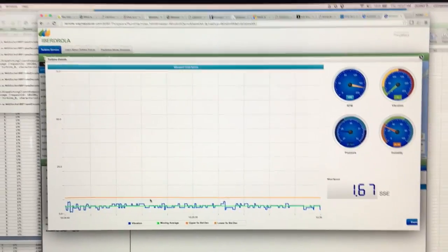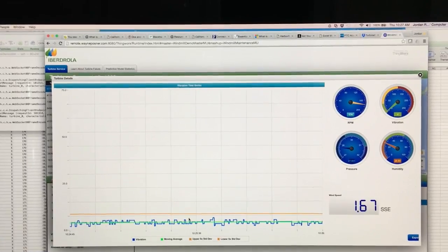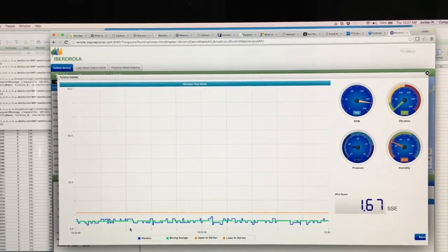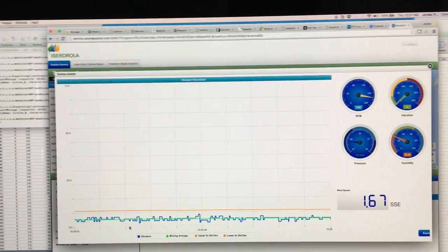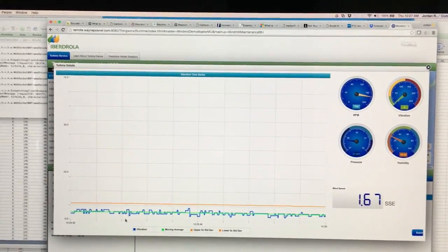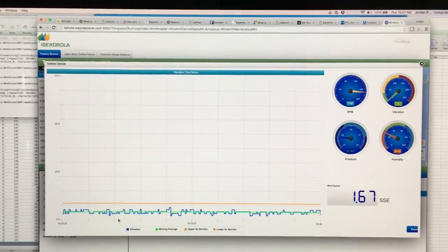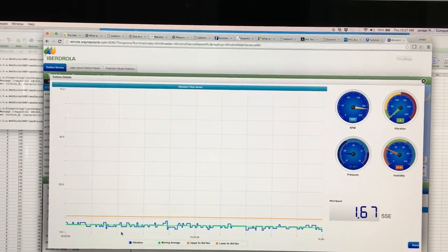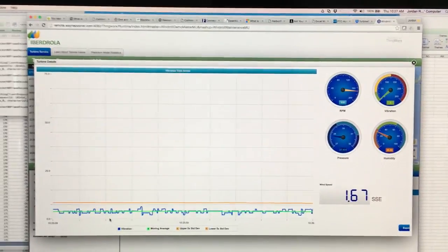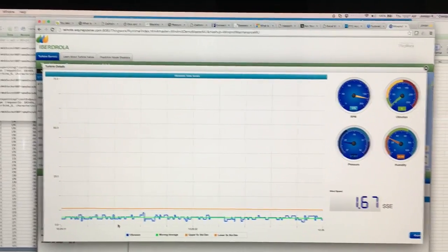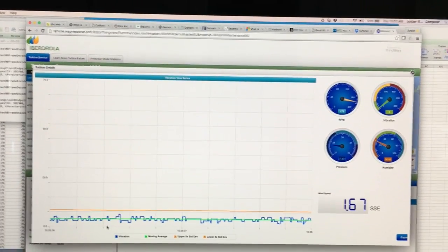Then the green line is a moving average over the last 20 minutes, and the orange line is an upper Bollinger Band, which represents 5 standard deviations added to the moving average. So if that blue line tips above the upper orange line, that means that there is an event that would not occur any more than 0.3% of the time, or whatever the standard deviation math is. I think that's right. So I'm going to go to the turbine model that's spinning right now, and I'm going to simulate a vibration. We're going to see what happens over here in the graph.